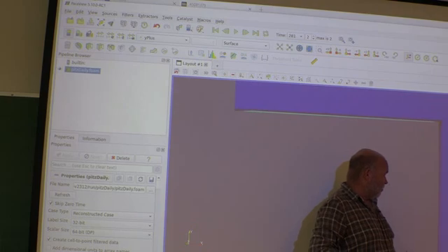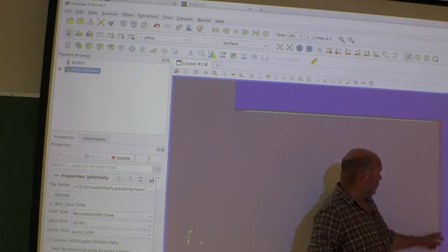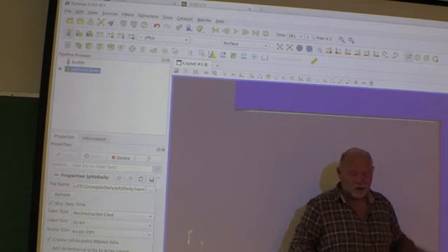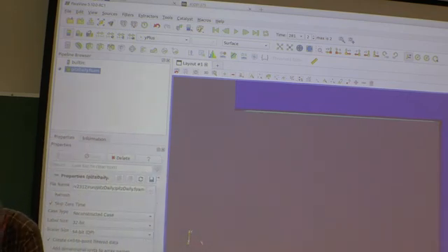Okay, here it might be small, but here the velocity isn't quite small anyway. So this one is not a problem. This is actually a problem. So the mesh is not good. The mesh is not good. So there you see the mesh here. We can zoom in a little bit more.